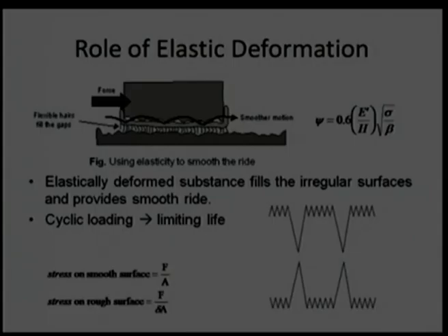We know other than iron or ferrous material, not a single component has any endurance strength. That will be continuously decreasing. A component can tolerate much lesser stress at a high number of cycles. So, almost all the components other than iron will have limited life.